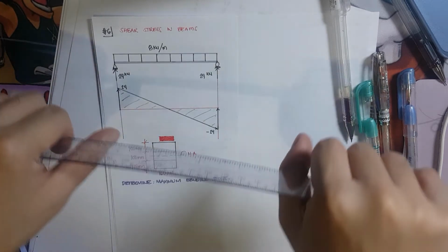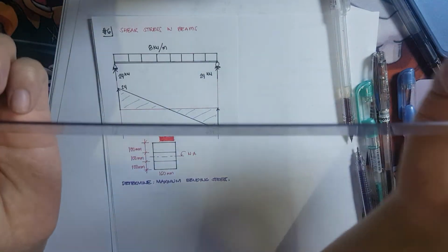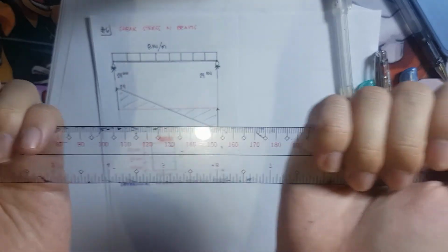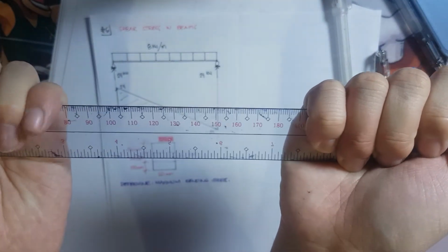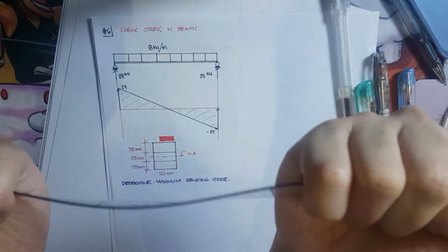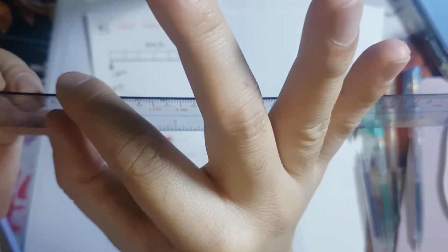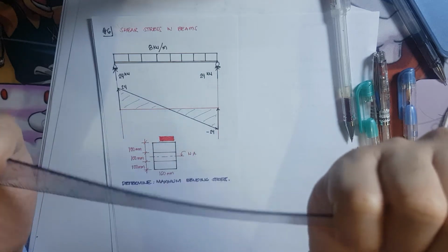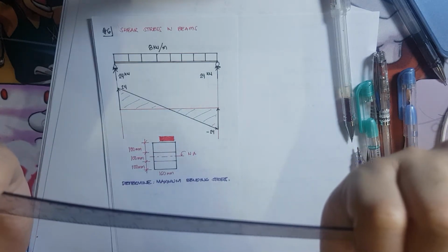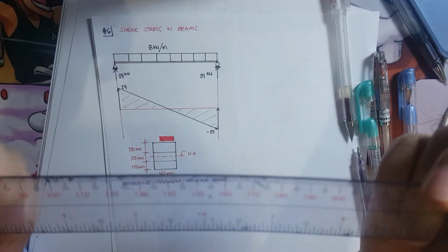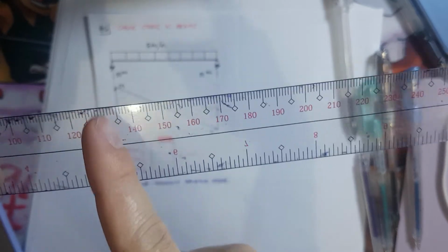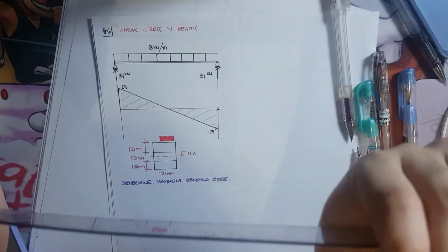Like what I've said a while ago, or in the other video, if I have here a beam and I am to apply a downward force, there will be a bending. The stress above is the normal stress, which is in compression, and the stress below is tension. Those two forces are causing the bending of the beam. But bending stress is not the only stress present. We also have the shearing stress, or the shear stress, if loads are applied.